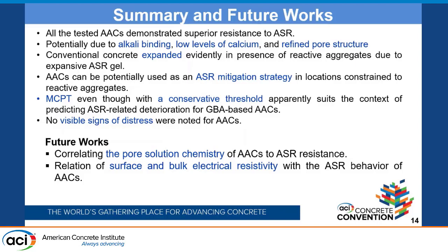MCPT, even with the conservative threshold of a very thin band, the 200 to 250 microstrains, apparently suits the context of predicting ASR in ground bottom ash based alkali-activated concretes. And lastly, we didn't see any visible signs of distress for these alkali-activated concretes. The future work would be correlating the pore solution chemistry with the ASR behavior, and also relating surface and bulk electrical resistivity parameters with ASR.